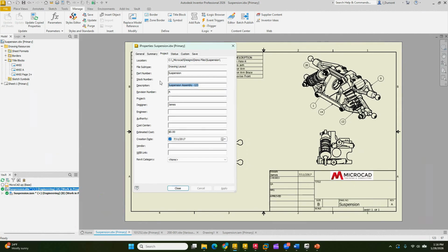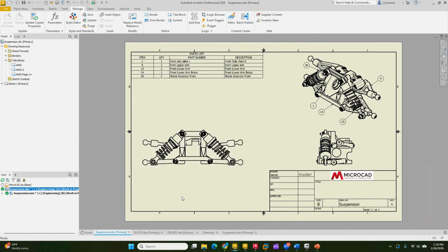And I've got users on this call that I know that their assemblies are massive, and this just is not realistic. What we want to do is add automation to this. And what we want to do is just save the drawing, and then that save should bring in all the data. And if we look at iLogic, for those of you who have never seen this before, this is your model browser, and that little plus sign right to the right of model allows you to get other panels that are available, and one of them is iLogic.